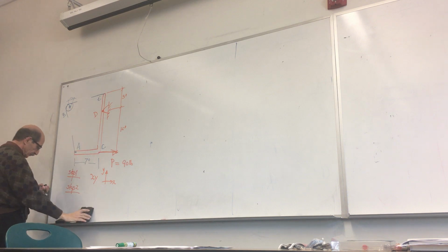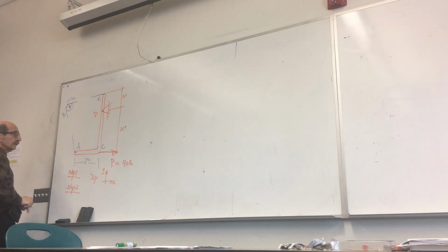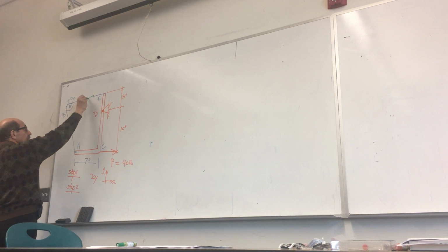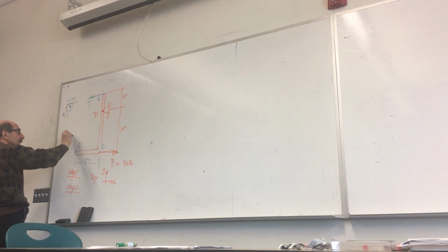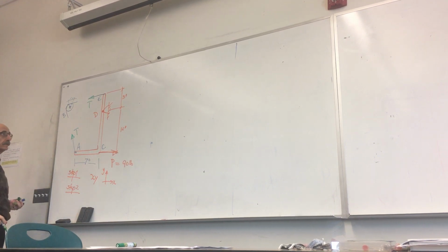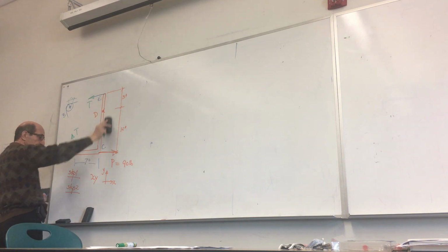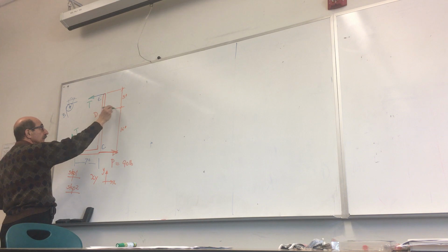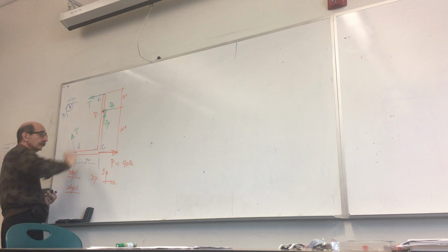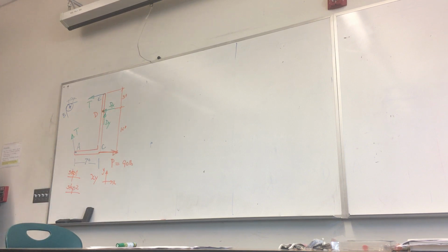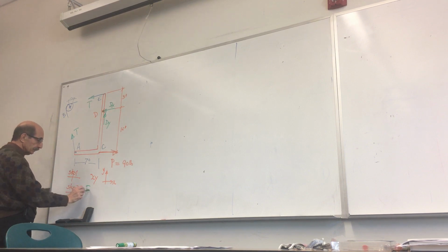In other words, there is the same force in that cable here and here. How about here? If I remove this support, that represents two unknowns. Let's assume these two unknowns are this way and this way. So that is the free body diagram. Step number 2.